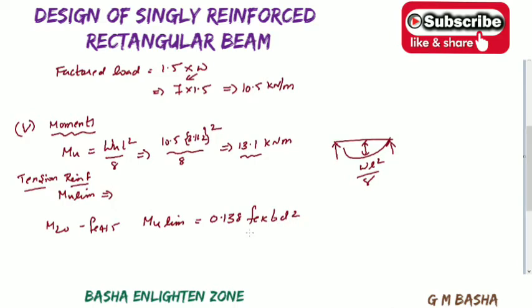It can be obtained by simplifying the other formula, 0.36 fck b d into the lever arm, d minus 0.42 xu. If you substitute the values fck 20 and fy 415, you will get this directly. So it is better to remember that for M20 grade concrete and Fe415 steel, your Mu limit will be equal to 0.138 fck bd square.